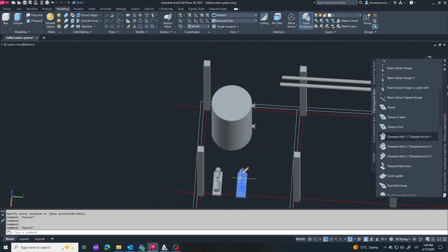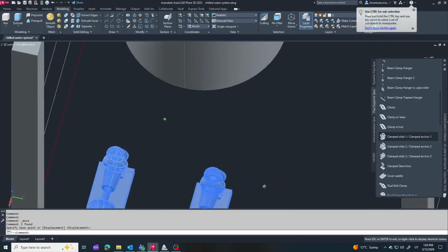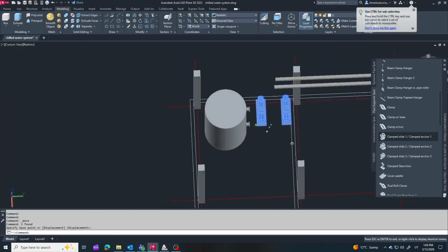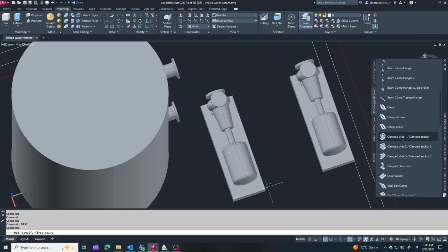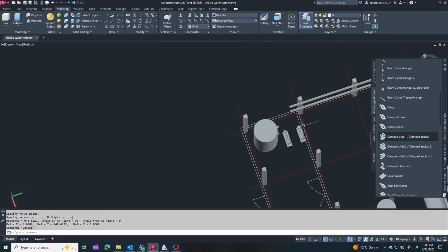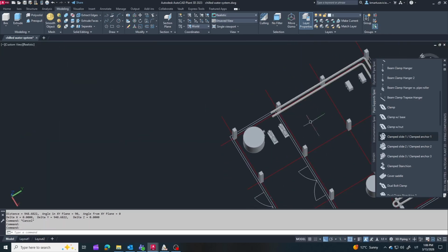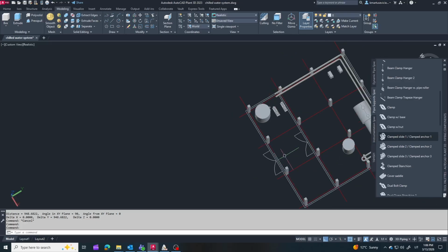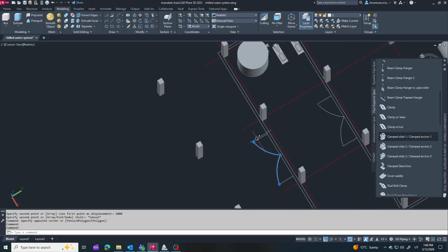The loop is now ready, but I will relocate the pumps to create a better maintenance area and overall layout. Even though the system is circular, the pump position still matters. The pump suction side should take water from the buffer tank, where the chilled water is available for circulation. The pump discharge side should go toward the users, because the pump's job is to push the chilled water through the system and overcome the hydraulic resistance of the piping, valves, and equipment.